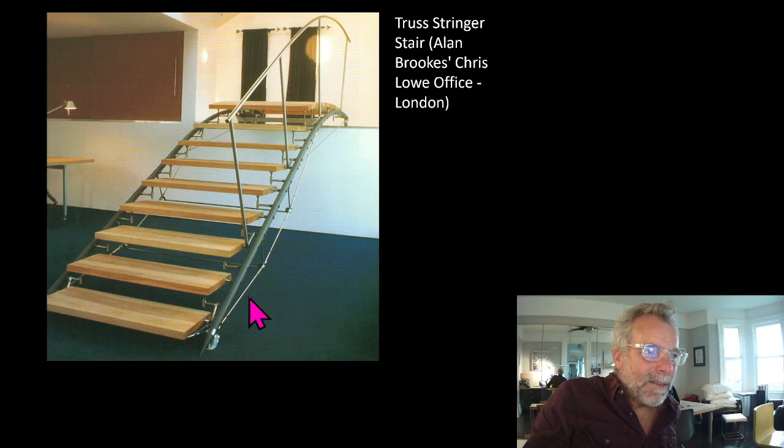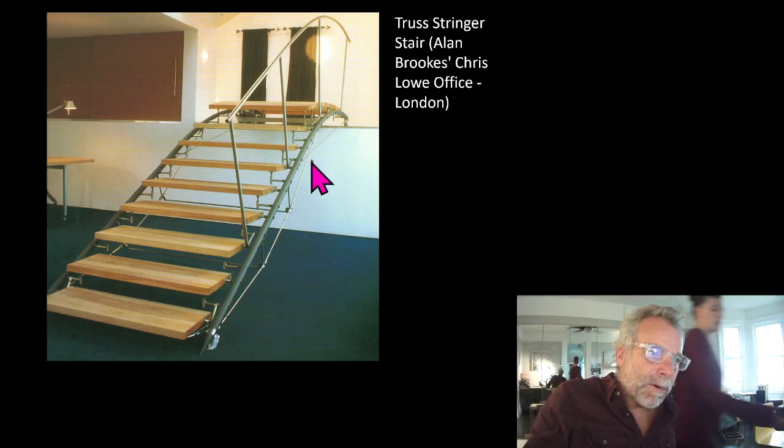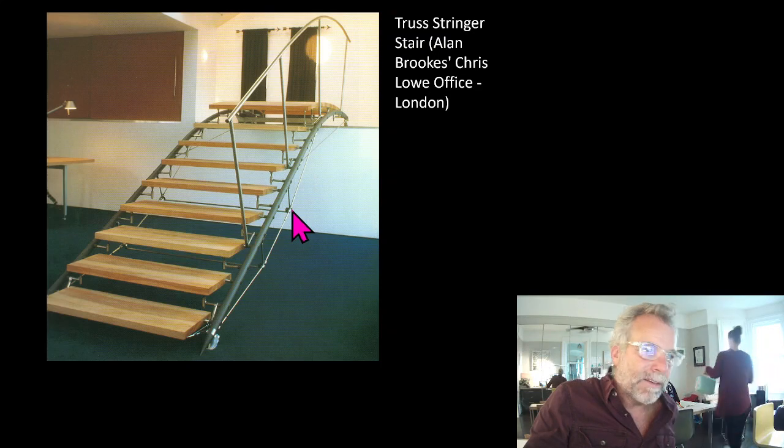So this is a really lovely, interesting stair. It is not entirely clear to me where this stair goes to, but again, very tectonic. You can see this one they've created. This pipe is obviously too shallow to act as a stringer, and yet they've used it as a stringer by introducing this bowstring truss underneath to stiffen it in flexure.